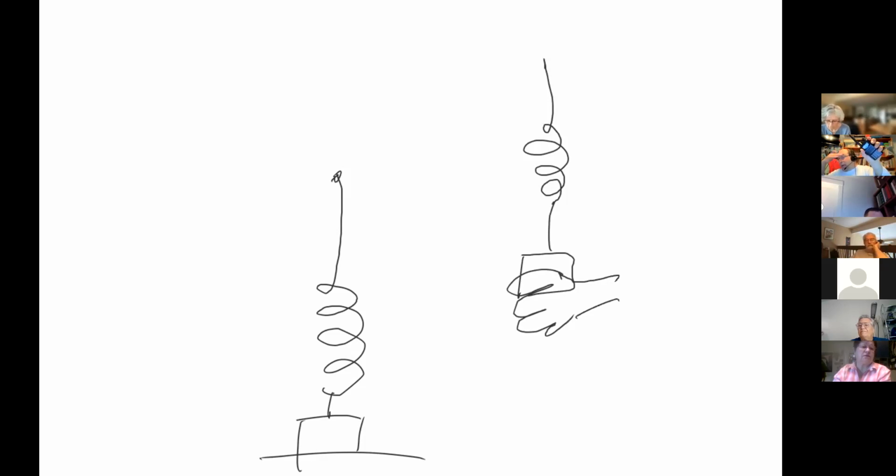Basically, I am the other half of the antenna when I'm holding it, and it's actually capacitively coupling to me. I am the other half of the antenna, which is also why I don't like operating at particularly high power. It's not going to hurt you, but I don't particularly want that much RF current going through me.